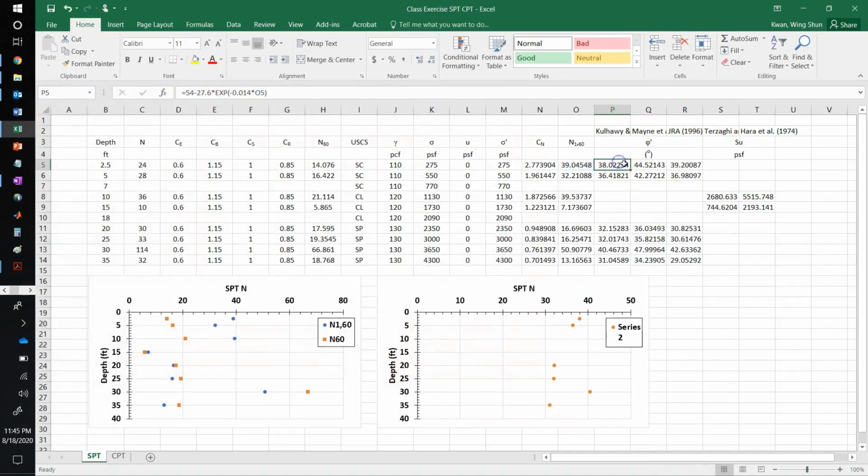So I find the friction angle for the sand from the SPT and also try to estimate. You need to use this with a lot of care. At the end of the day, when I practice, the SPT estimates will just be on my calculation paper.